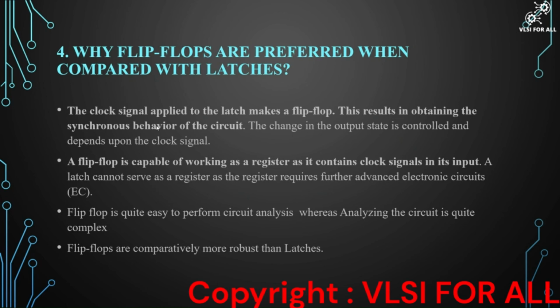Next point: a flip-flop is capable of working as a register. Yes, because it contains a clock signal. In a latch, we do not have clock signals, and if we want to make a latch work as a register, we require further advanced electronic circuits. Flip-flop circuit analysis is quite easy because we have a clock signal. If we give the clock signal enable, the output changes accordingly, so we can analyze it easily. But latches are not like that, and flip-flops are comparatively more robust than latches. You understand, right? That's why flip-flops are preferred more when compared with latches.